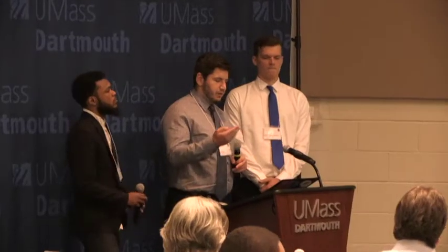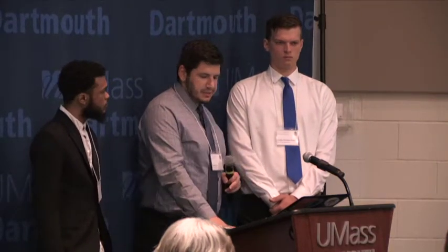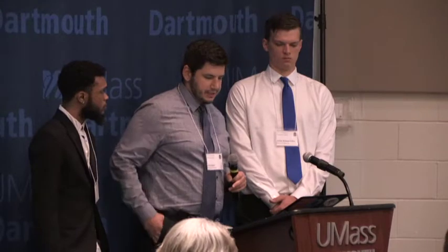We walked all 4 flights of stairs up, and we were at 43 feet. And then we walked all the way back down. We ended at 5. So every single time we noticed it incremented by 9 to 11 feet. So it was pretty spot on. And that was using the delta time of 2,000 milliseconds and delta pressure of 0.01.